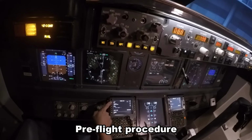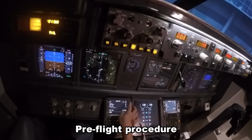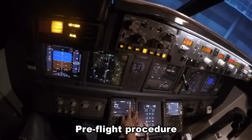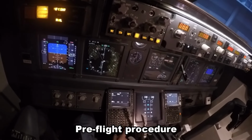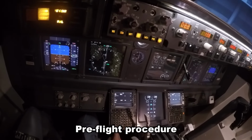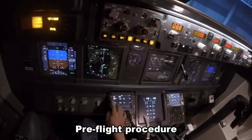Takeoff ref will have flaps 5, center of gravity will be 23.5. So our V speeds, V1's 128, VR is 129, V2 is 141. We'll just quickly put in our fixes. We'll have fixes at 7 nautical miles and 10 nautical miles.